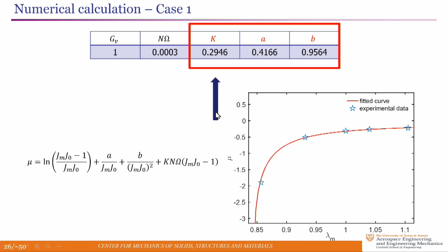First case is just the swelling problem. Swell it until it reaches equilibrium, or dry it until it reaches equilibrium, and find the connection between the chemical potential and the final dimension or the stretch size of the specimen. The stars are experiments. The line is the calibration curve that passes through. As a result, you calibrate the bulk modulus K and the 2 constants in the Flory mixing model for the free energy. And so you can calibrate those constants.